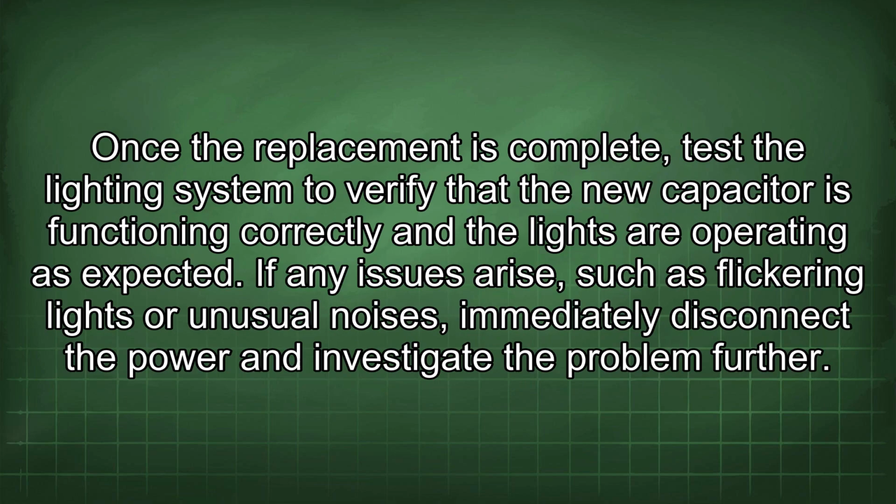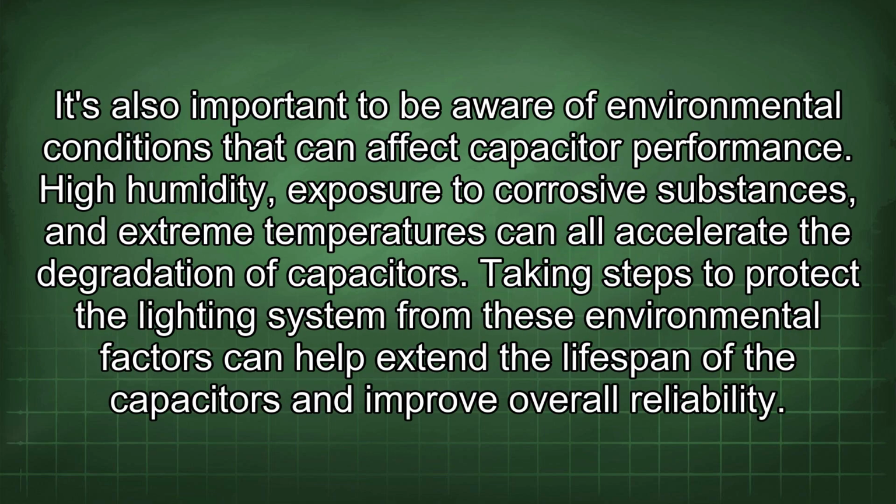Once the replacement is complete, test the lighting system to verify that the new capacitor is functioning correctly and the lights are operating as expected. If any issues arise, such as flickering lights or unusual noises, immediately disconnect the power and investigate the problem further. It's also important to be aware of environmental conditions that can affect capacitor performance. High humidity, exposure to corrosive substances, and extreme temperatures can all accelerate the degradation of capacitors. Taking steps to protect the lighting system from these environmental factors can help extend the lifespan of the capacitors and